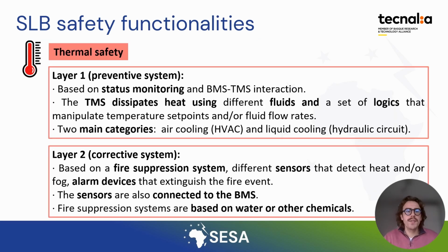Second life battery safety can be divided into two main types. First, thermal safety, and afterwards, electrical safety. Thermal safety is made of two main system layers. The first layer is a preventive system built of the BMS and TMS interaction, and it is based basically on the constant status monitoring by the battery management system and the communication with the thermal management system.